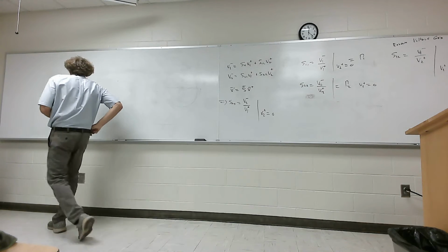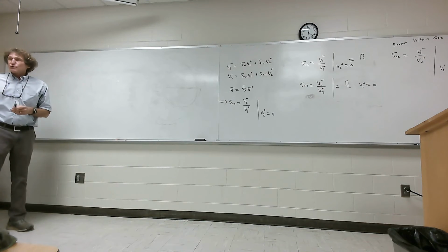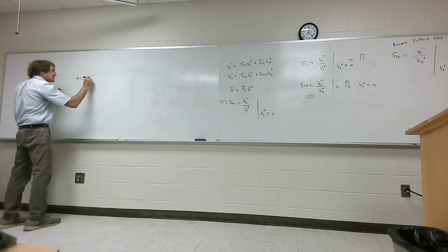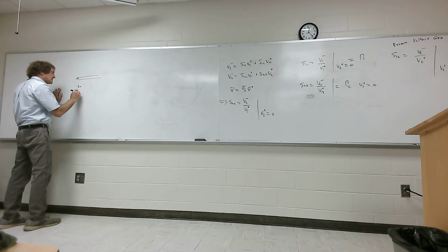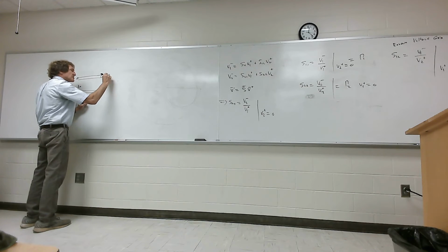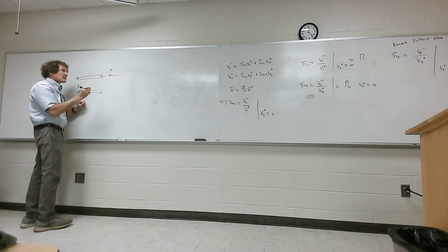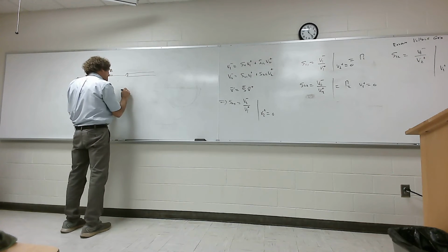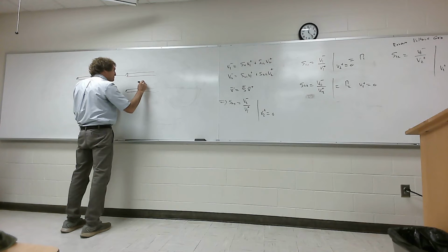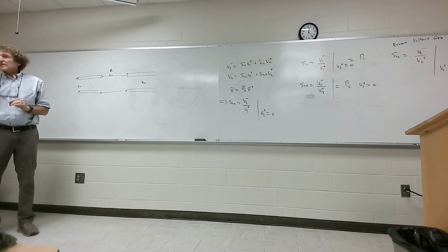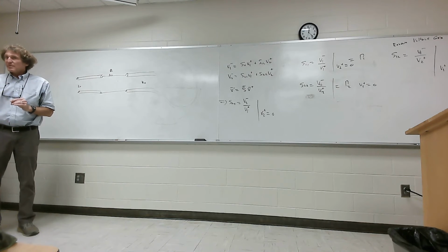Okay. Now pay attention to this one because there's one subtle trick that happens. That's something you don't see unless you're really paying attention. So I have a transmission line over here that's got a characteristic impedance Z0. Then I'm going to just put a resistor here, R, not anything else, then connect it to another transmission line that has a characteristic impedance Z0. And now I want to find out the S parameters for this system. Y'all hear me on this one?